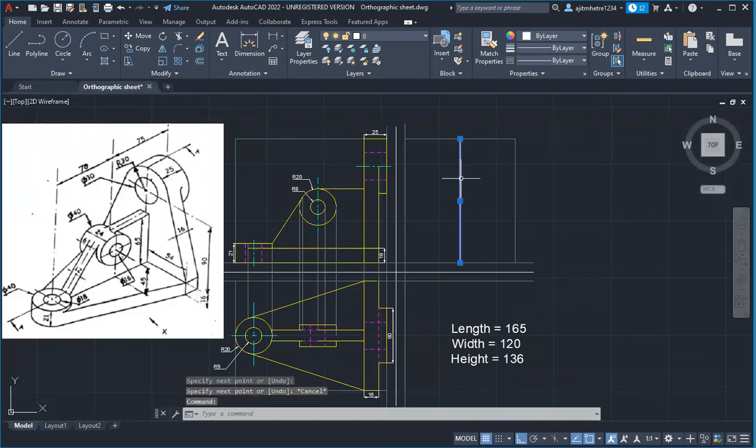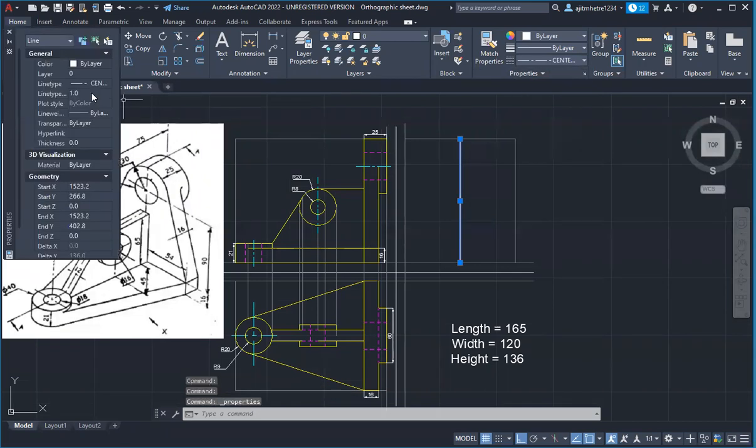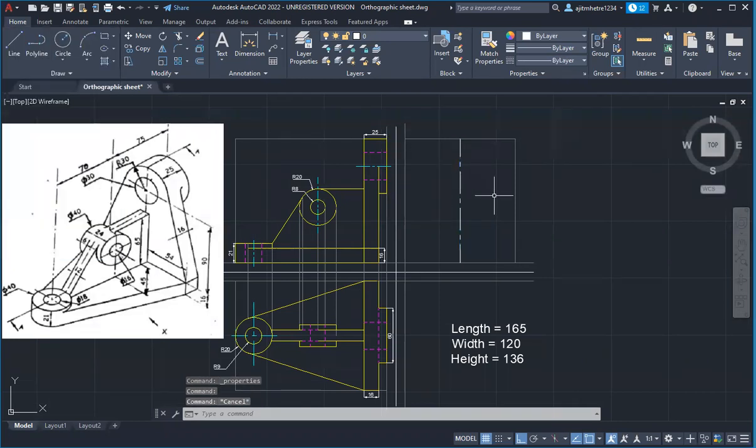Whereas the diagram is symmetrical, it is a little helpful for us to convert that whole thing into a half. So this is the center line. Okay. Now, what we will do is we'll take the projection of the center line in here.